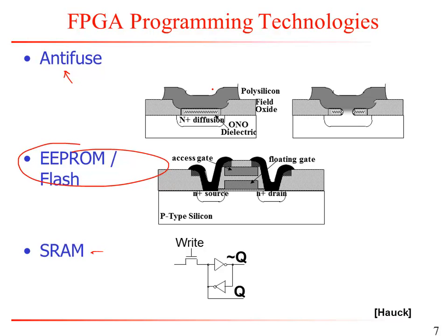And basically using this method you can program the chip. The good thing about it is it's much faster compared to SRAM because you're not using things like pass transistors and stuff like that. But the bad thing is you can't reprogram. So once you burn the chip, that's it. If you find a bug, then throw it out. You have to use another chip.